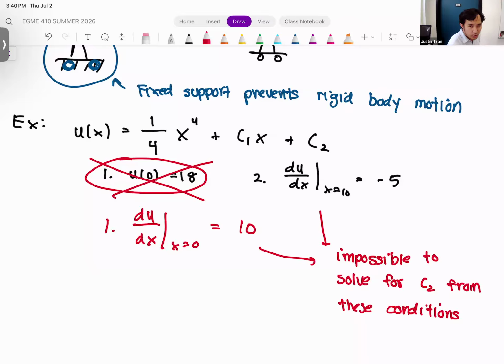So mathematically, the constraint type boundary condition is required as well. Because when you solve a differential equation, there's inevitably going to be a constant, which I call a bias term or a reference term. Without a constraint type boundary condition, it's actually impossible to solve for that value. So a constraint type is always going to be required. There's no getting around that at all. You can't run an FEA simulation, and you can't solve a differential equation, without at least one constraint type boundary condition.